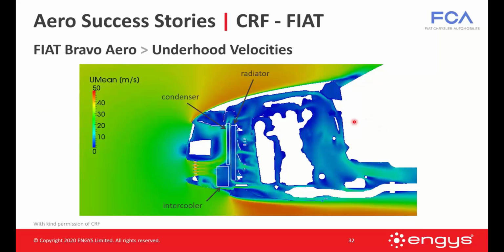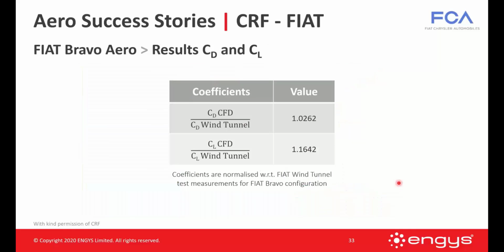One of the important comparison points was looking at the underhood velocities. The potential customer in this scenario was interested in looking at the underhood flows, looking down the road at underhood thermal simulations. So we're able to actually capture a lot of this information and reflect that into a design phase if we need to know a certain amount of flow or convective cooling over different engine components.